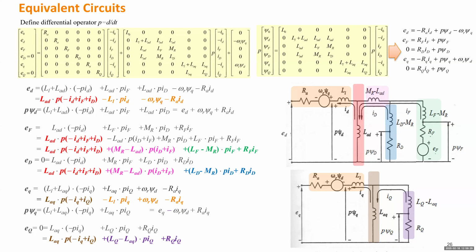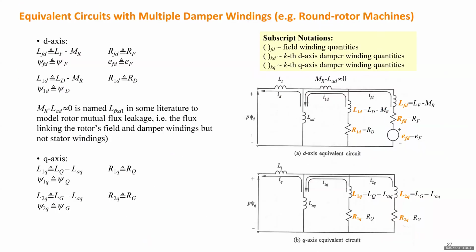If we come to the ground rotor, for that DC source for the D and Q axes, it will also be on that circuit. But there is only one DC source, which is the field winding. There's no other DC source at all, because that's the only input of the entire model, the entire system.